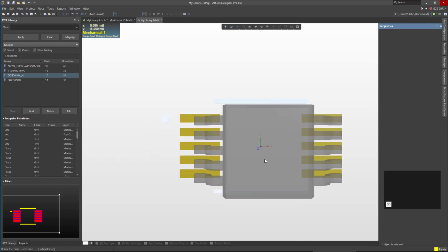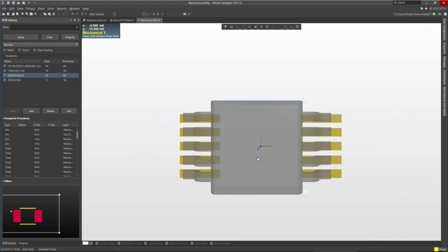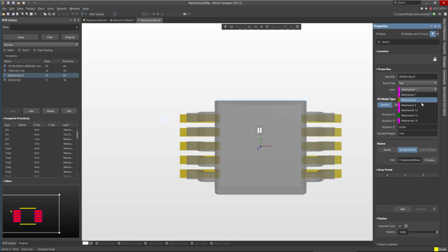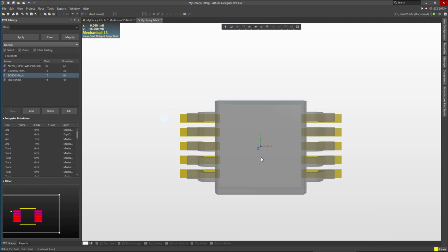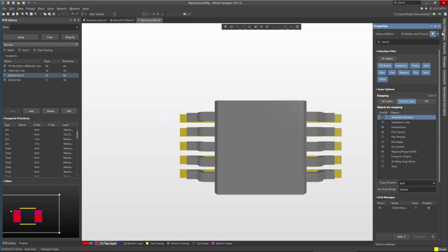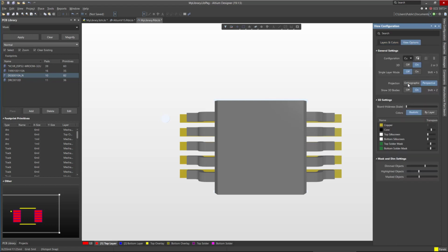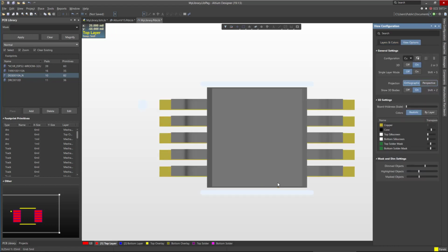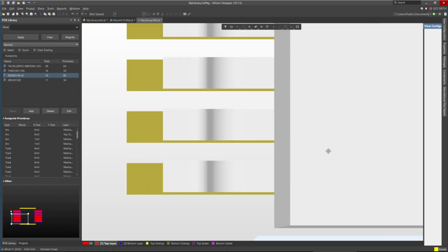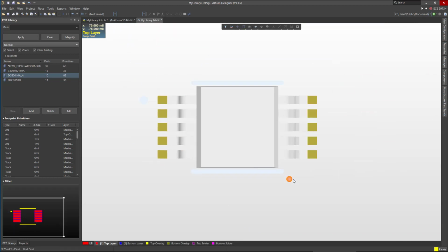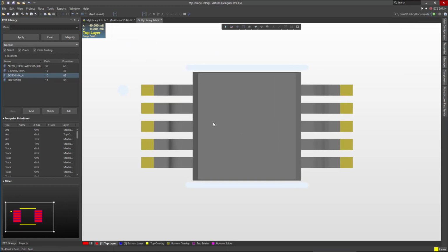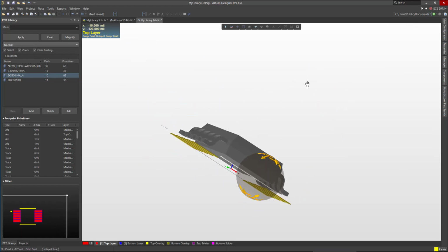So, and what layer do you want to use for the 3D model? Usually it's better to use layer 13 for that, because all other libraries use layer 13, and we'll talk about that in the next session. So click on it. Now if you go to the properties of view configuration and click on orthographic, you can see if they are aligned or not. So what you need to do is align it, but if you move, here we go, just drag and drop it, it looks well aligned, and you can take a look at it.